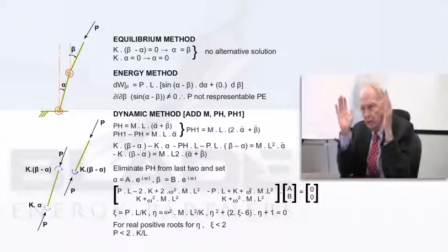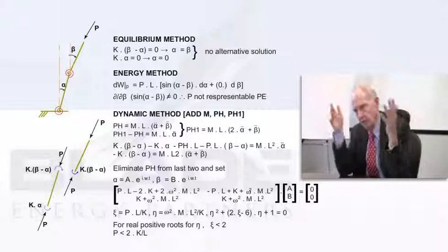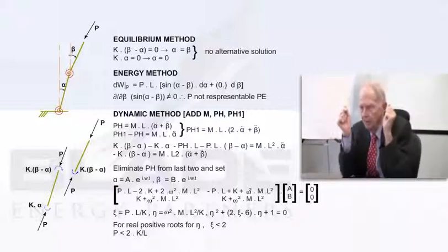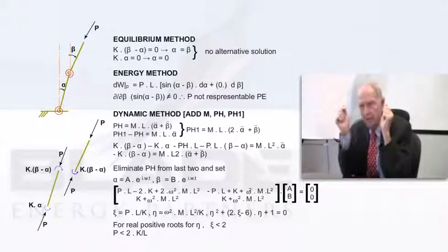It's got the load on, the load is constant, it's just sitting there, and we're going to assume for this first little bit of talking that it's below its buckling load. Then I come up to the top and I push a little bit sideways, and then I let go. Does it come back or not? If it comes back, that's another way of looking at stability, and it's a way that many books do.